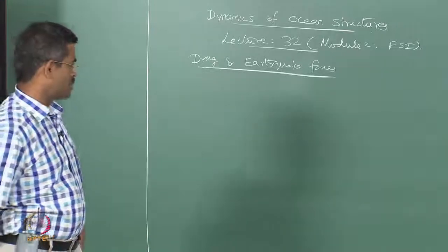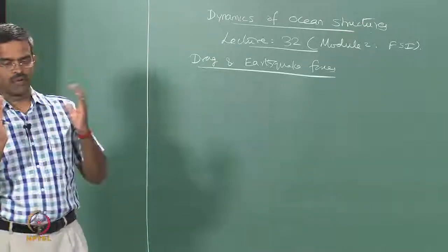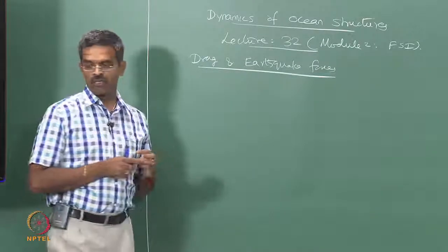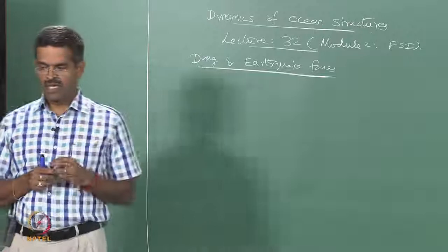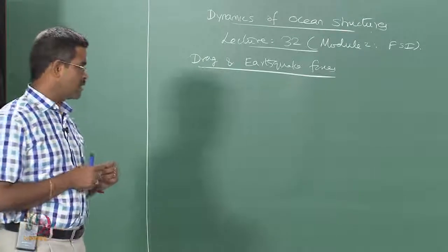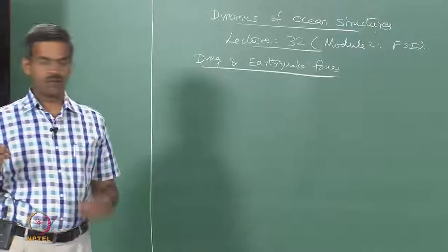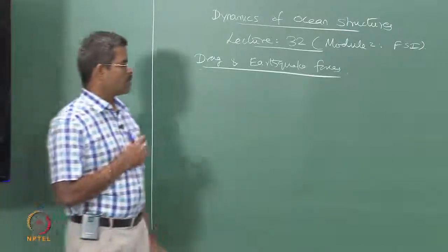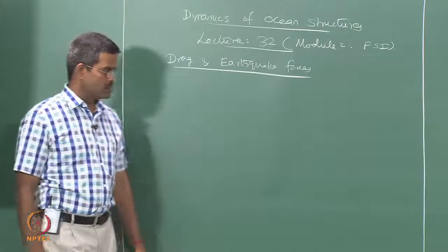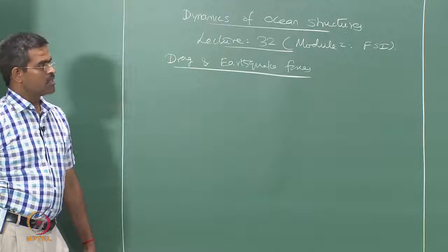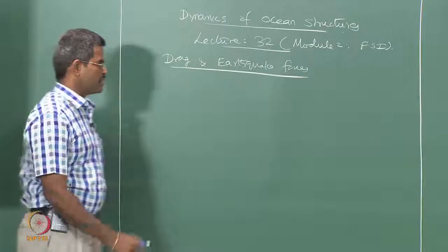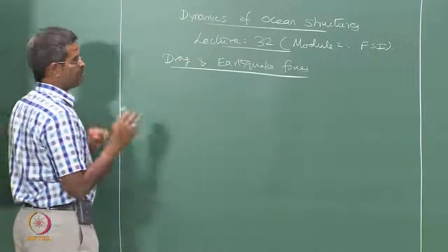Subsequently we said how this alteration or velocity variation can be captured to understand the force reduction on a given member by simply putting an outer perforated cover on an inner shield of a cylinder, so that the force on the inner cylinder is reduced. This can be considered one of the effective methods of retrofitting or rehabilitation of the inner cylinder, provided the inner cylinder is not replaced because of its damage, but only an encapsulating cover is put outside the cylinder in a specific zone damaged by the splashing effect or corrosion effect. So, now in all these cases one is interested to ultimately get to an important point.